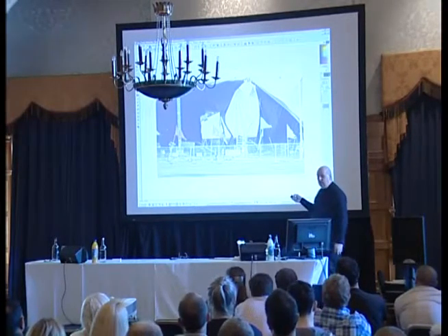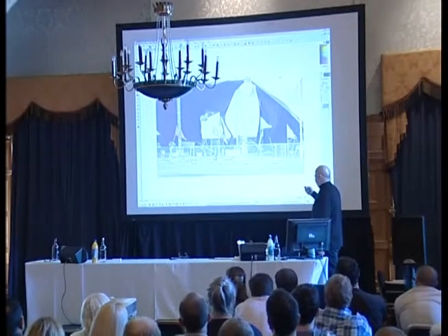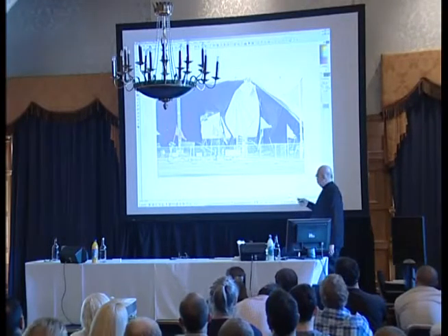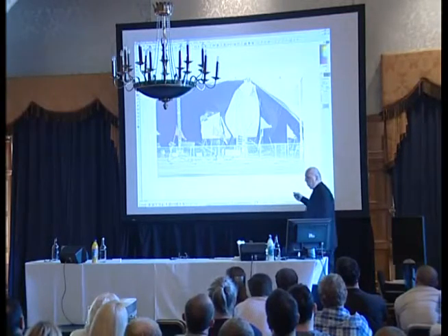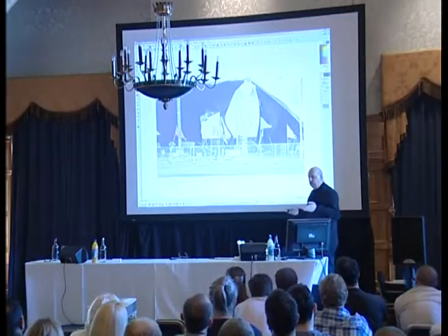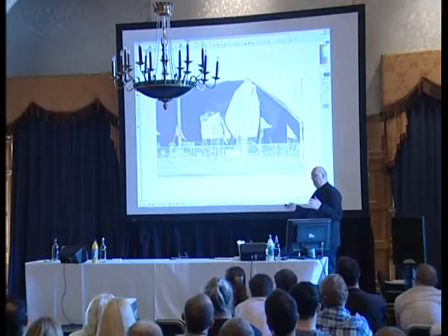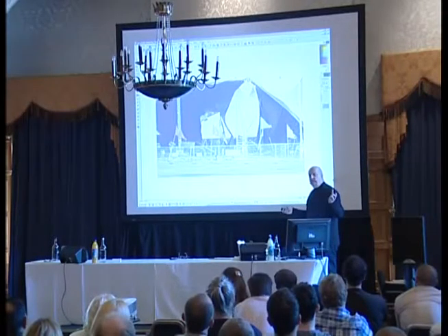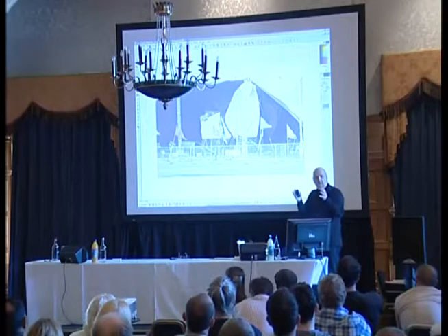And the wind speed wasn't more than 20 metres a second at the time. That ripped because of the tension in the roof. And there's numerous examples we could make of that. And once again, on a big top, it's a topical thing because people are talking about making sure cables are tight. And you can actually induce failure in the king poles if you don't leave the main guys slack when the roof's up. You need to let the membrane just breathe a little and let it move.